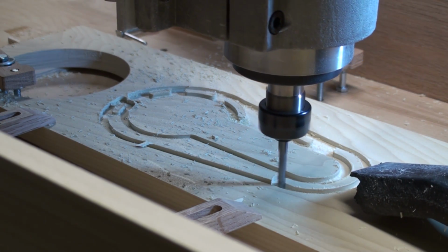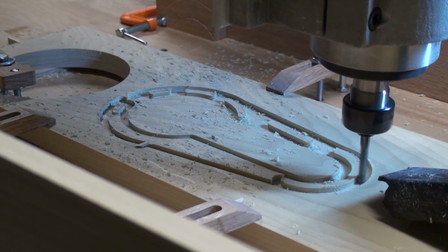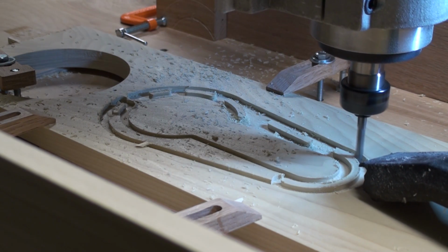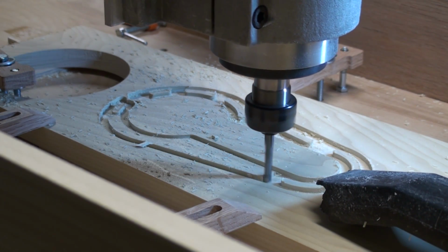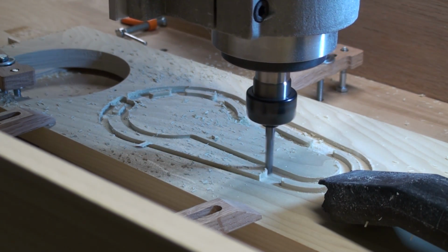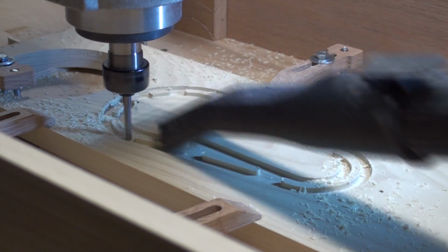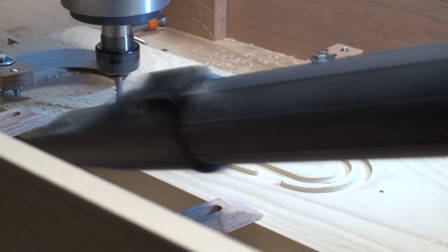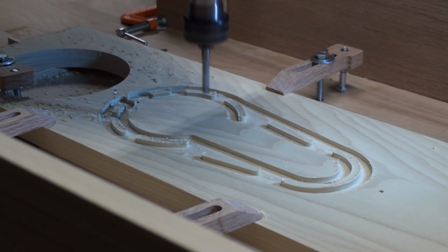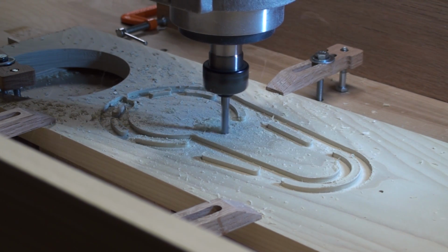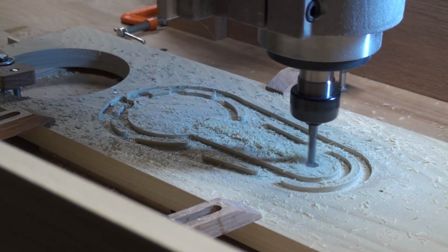I'm cutting it in 4mm thick slices, so since the ridge edge is only 4mm thick, I only need one pass for this depth. This bit is big enough to do this in one pass with this speed without breaking the bit. And so after the first pass is done, it will immediately go to the second toolpath, as it is exported in a single G-code file.